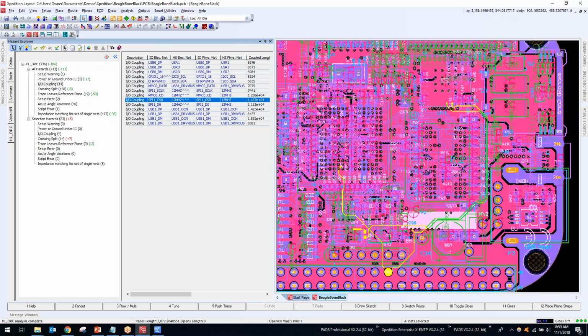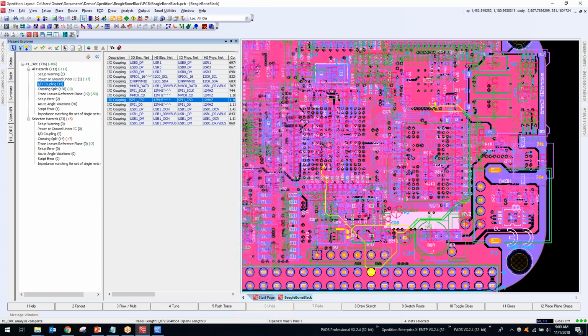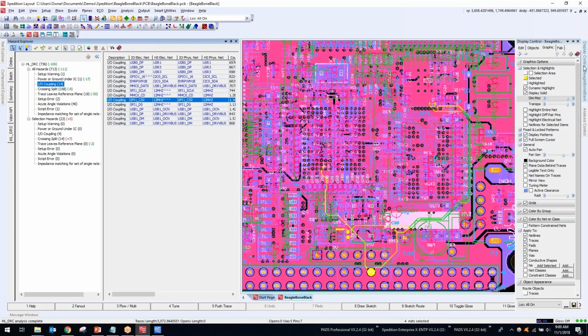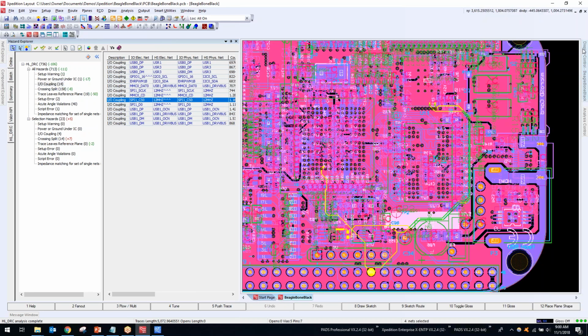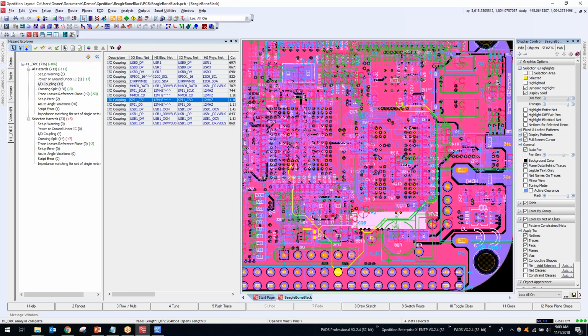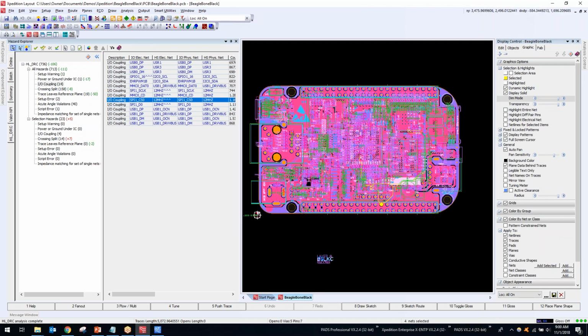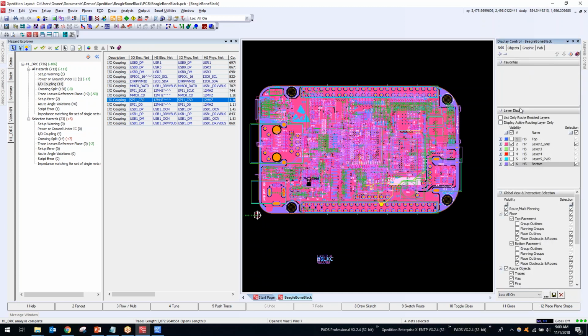Okay, so in order to make these a little bit easier to work with in C, I do want to offer some tips and tricks while using the display control in conjunction with the Hazard Explorer. Okay, so I have worked with a lot of customers that get a little intimidated by the display control just because there is so much information going on within here. Okay, so if I have this section tabbed while I have my Hazard Explorer, this can be a very effective way to easily identify the issues that I have in my board.